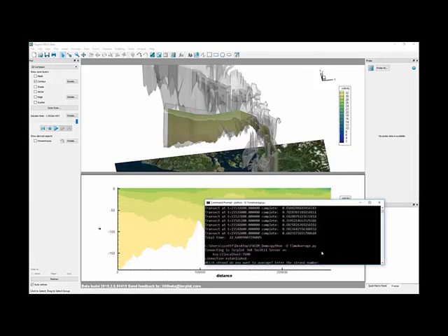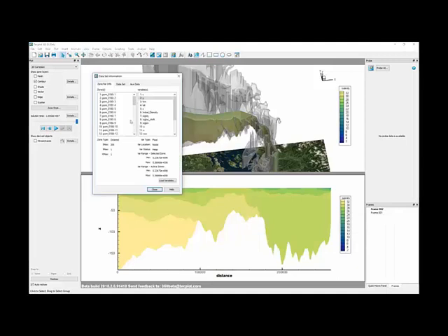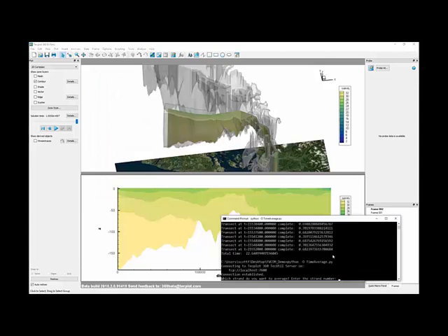And so what this script does is it asks, well, which strand do you want to average? Remember, we looked at the dataset information dialog earlier, and we pointed out the strand index. So we want to do the time average of my transect. So let's go into the dataset information dialog and find out what strand number that is. All of our transect zones have the same strand number. That's strand number 2. So we'll come back into the command prompt, and we'll just type 2.